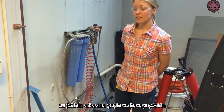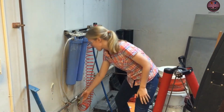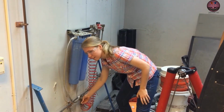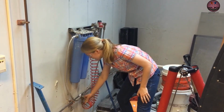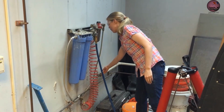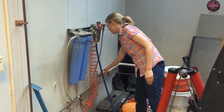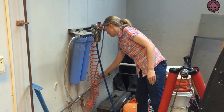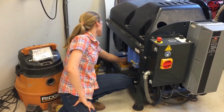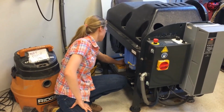Next, go behind the water jet and turn the air valve counterclockwise to the 6 o'clock position. Next, turn the water valve counterclockwise to the 9 o'clock position. Next, turn this red switch clockwise to the on position.